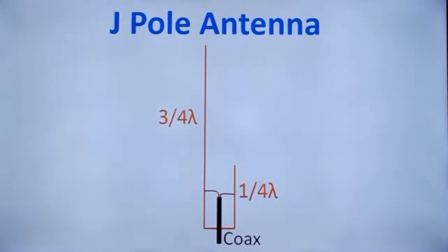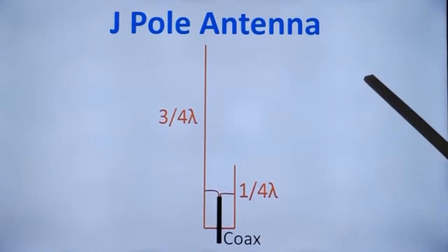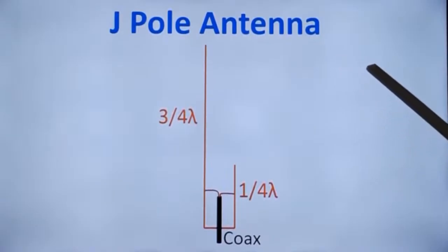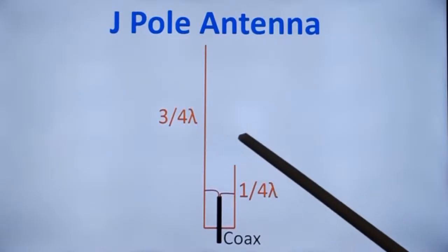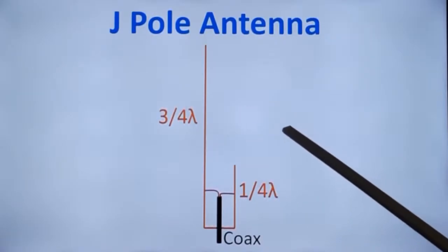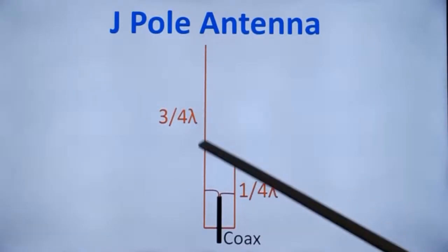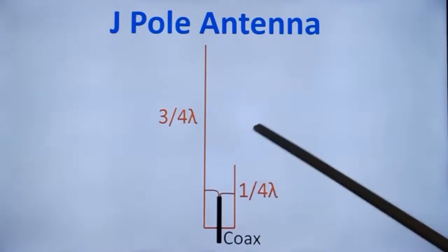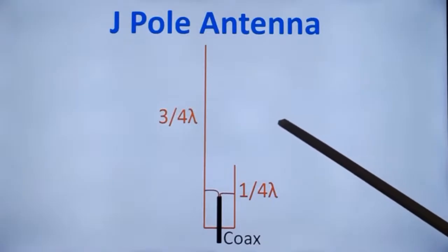The usual amateur 2 meter band and amateur 70 centimeter band are like 3rd harmonic. That is, a 2 meter antenna will also resonate as 3rd harmonic on the 70 centimeter band. So this can be used as a single antenna for satellite communication for favorable passes.